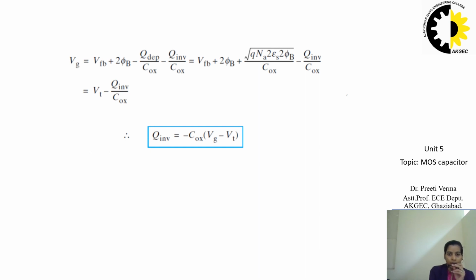So we can understand this problem from the MOS transistor structure. The inversion electrons are supplied by N plus junctions. The inversion layer may be visualized as a very thin N layer. Hence the term inversion of the surface conductivity type.